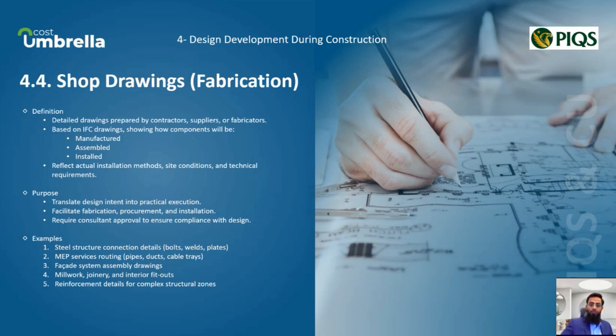For example, a structural IFC drawing may show a steel beam layout with its length, its label, and its location, but the shop drawing would include bolt hole location, weld type, and plate size for fabrication. Similarly, an MEP shop drawing will reflect real-world routing of pipes and ducts based on the actual site measurements and clash-free coordination.